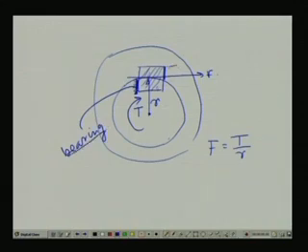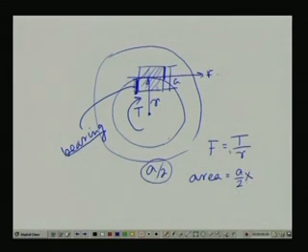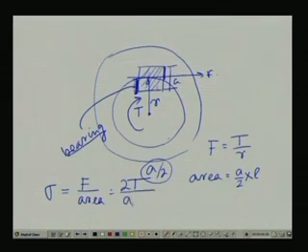The entire dimension was given as A, so this length is basically A by 2. What is the total area? The area equals A by 2 multiplied by the total length, which I suppose was given as L. So, we are getting bearing stress sigma equals force again divided by area, that comes out to be 2T by ALR. So, this is precisely how we get the bearing stresses in this manner.